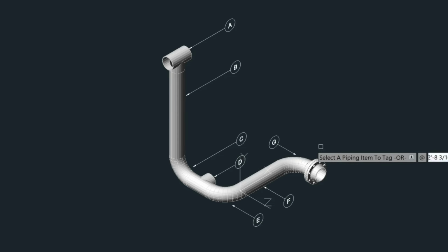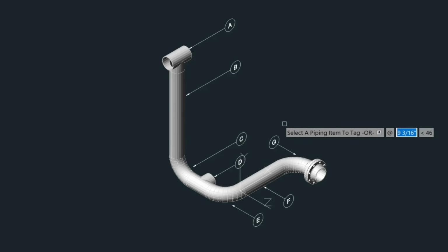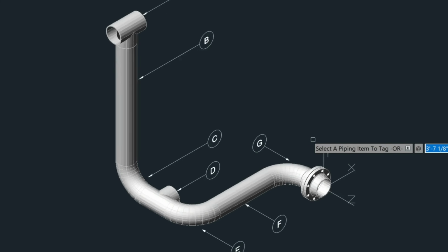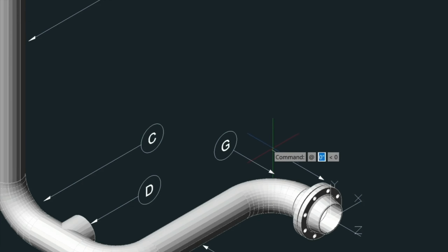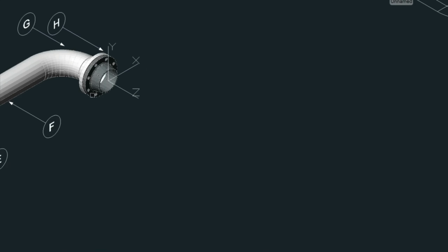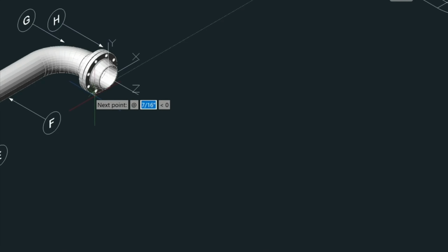Next we have the flanges. So we need to change the origin as we're rounding this bend here. And let's come down and make sure we select the backside one first. So we'll left click and let's place this one here. And then for the one on the front, to the flange itself, then the gasket and the bolts. Let's select it here at the flange, come down this way, and then do the horizontal option here.